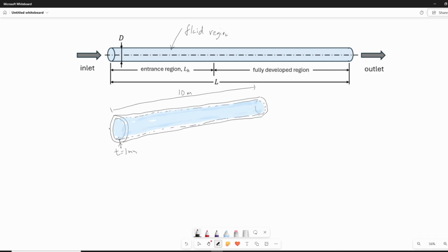That is why the diameter that we use here is the inner diameter, which represents the diameter of the fluid tube. If we extract this out, this is what it looks like. It looks like the pipe, but the diameter of the fluid is the inner diameter of the pipe itself. So this is what we will simulate.